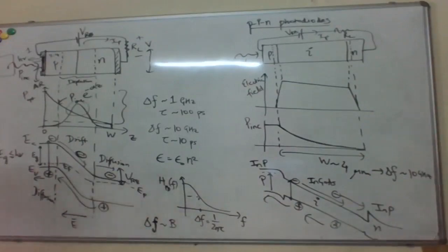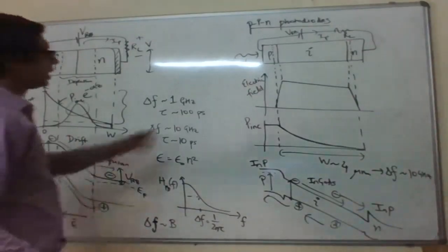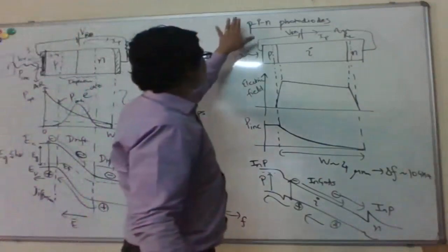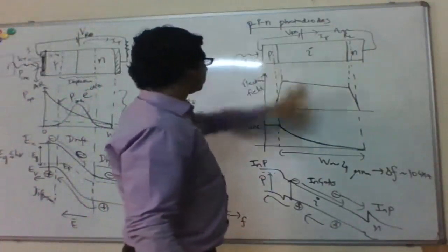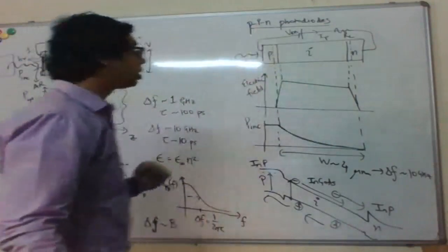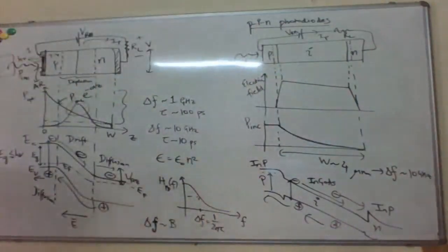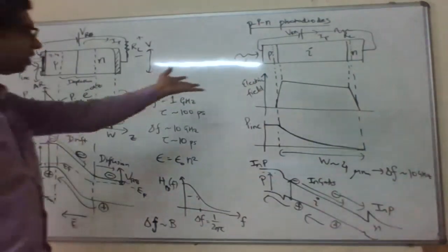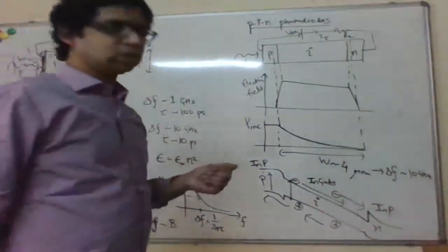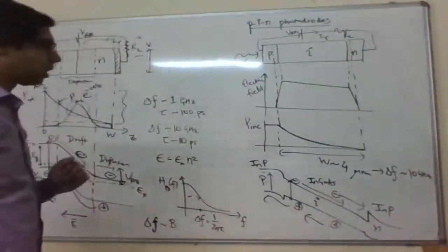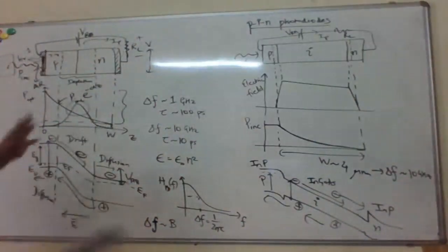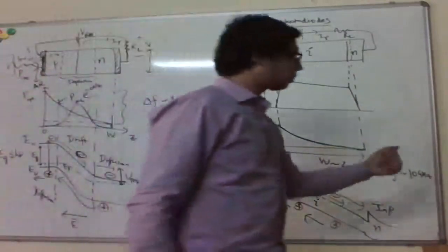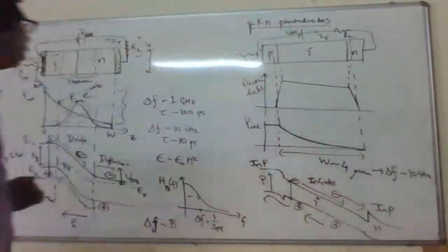Okay, so that's primarily the most popular kind of photodetector which is used, the PIN photodiode, right, which gives you responsivity of, as I said, close to 1 amp per watt at the telecom wavelengths, and with bandwidths of a few gigahertz, up to 10 gigahertz, let's say.